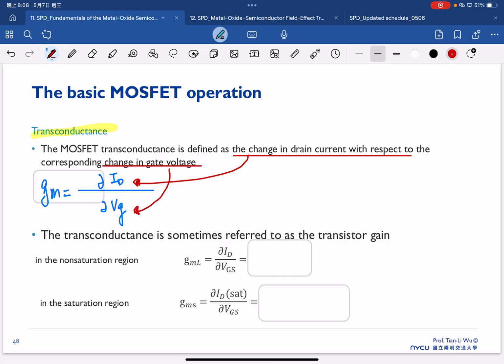So when you try to calculate transconductance from the ID-VG curve, where we have this typical ID-VG, once we estimate the transconductance, which is a derivative of the drain current versus the gate voltage, our transconductance plot, gm versus VG, will become this one.